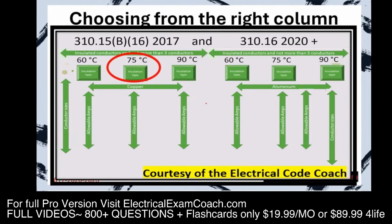Now, there'll be times that we choose from the 60, and this is where we start choosing from the 90. 99% of the time, you're going to choose from the 90 anytime that you're doing bundling adjustments or temperature corrections. We're going to choose from that 90° C column. We're getting ready to do practice questions, and you'll understand that more fully as we proceed.